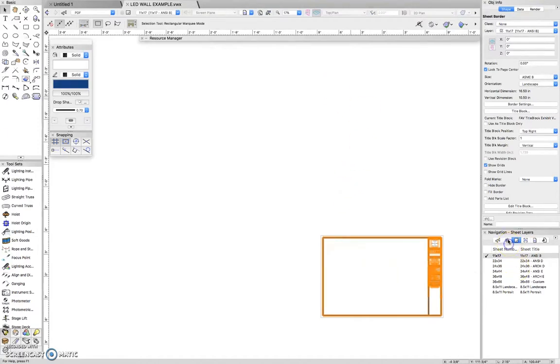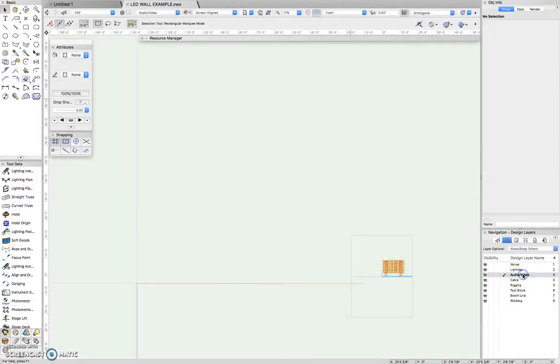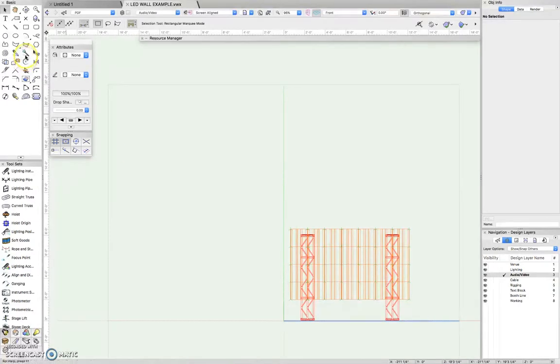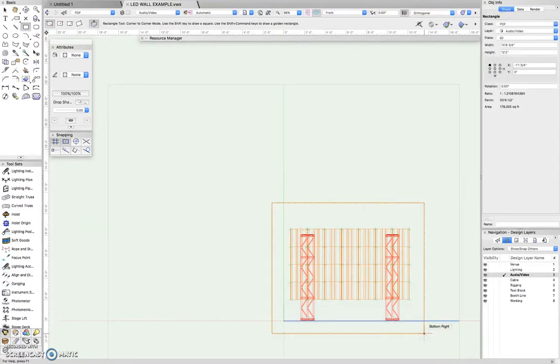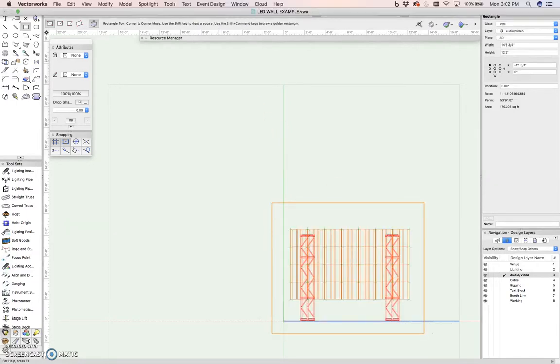So let's go back to our video wall. Click on one of your design layers. We're going to draw a rectangle that we're going to use as a viewport. I need to fix something, it's acting funny with these. So I zero out our fill and our lines. I'm basically drawing just an imaginary box around it. Number 4 is your hotkey for this, so you just draw a rectangle. This is basically your crop window of your viewport.